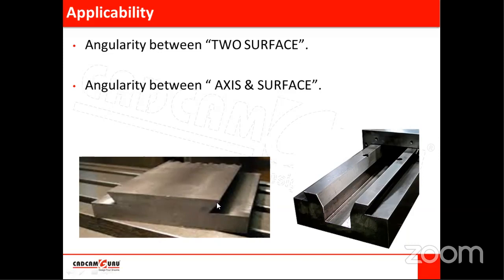So here at this location we are expecting a proper surface to surface contact, right? So at this location we want to maintain angularity, means that angle should be properly maintained, right, on both the sides. So this is angularity for dovetail slots and dovetail slides also.